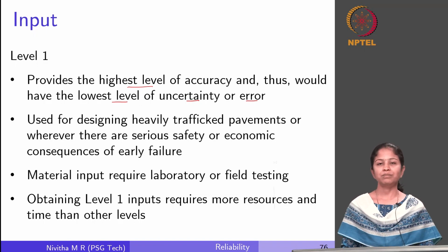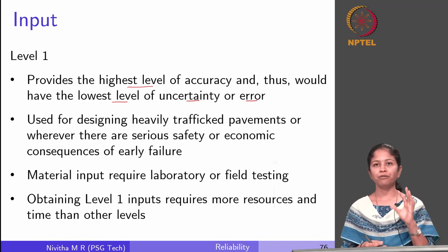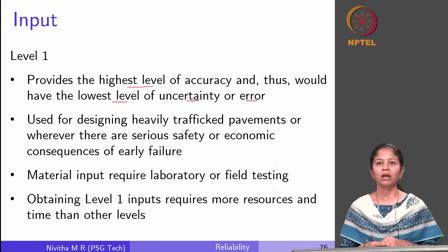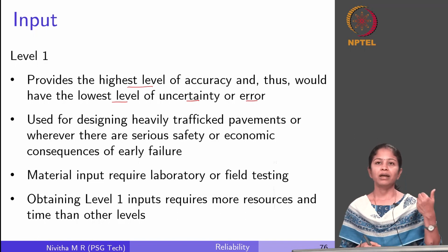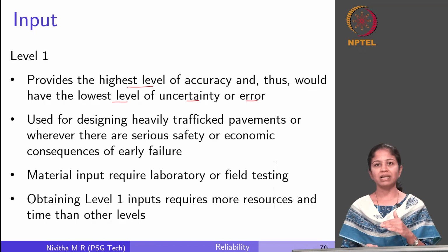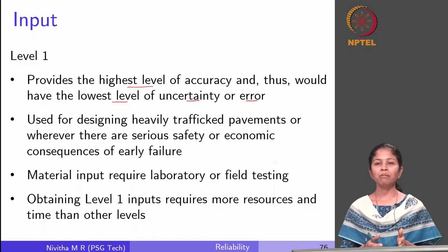Instead of making assumptions, I prepare a bituminous mix. Let us say dynamic modulus is the measure which is used for design for that particular bituminous layer. So how do I input the dynamic modulus? I prepare a bituminous mix sample as per the guidance, as per the codal provisions, and I take it to my lab. I conduct a dynamic modulus test on it.